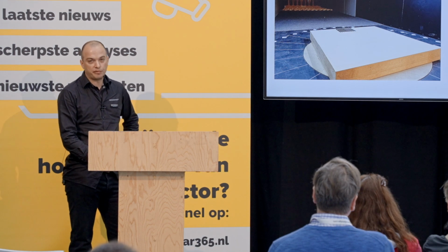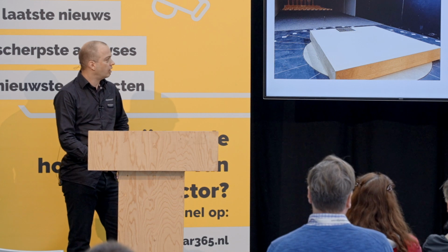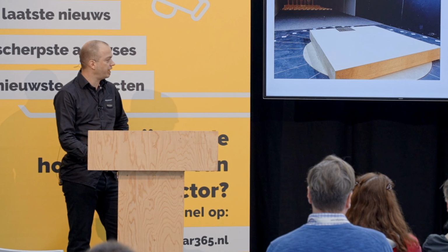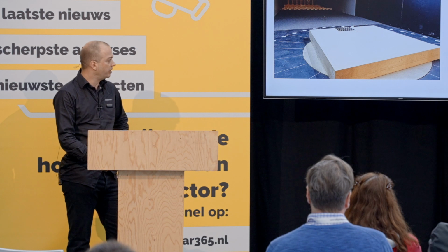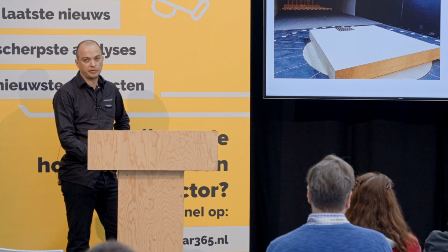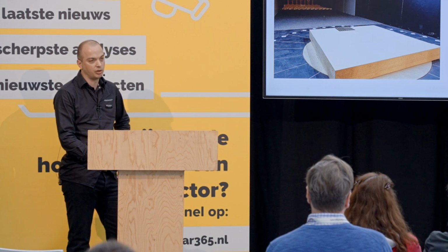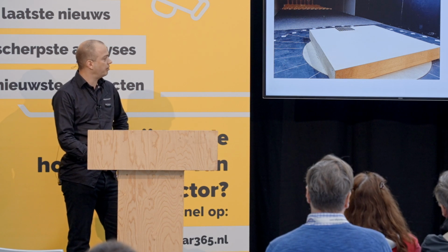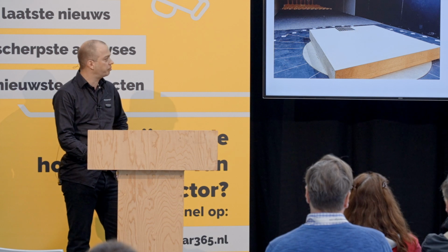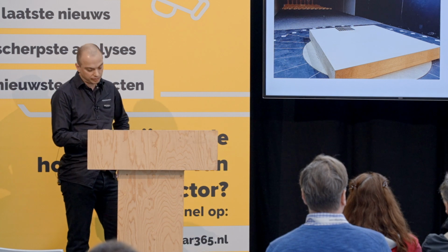So not all of you may be familiar with wind tunnel testing. So here's a nice picture of a wind tunnel model. You can see one solar array, which is placed in one part of a large industrial building. The building itself is placed on a turntable, which can be rotated. And in that way, the wind flow can be simulated from any wind direction. So you have to imagine that the wind is coming from the background to the foreground. You can see there built-in obstructions, the so-called fetch in the boundary layer wind tunnel.